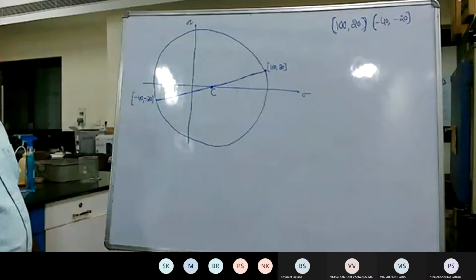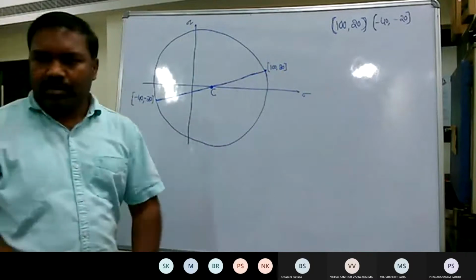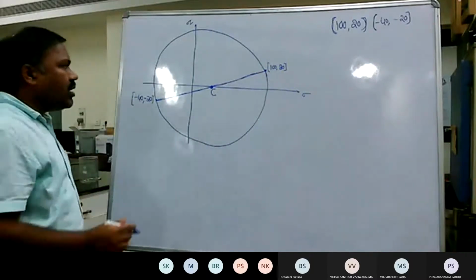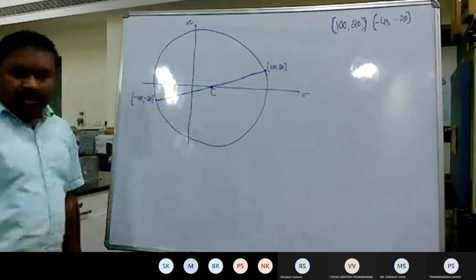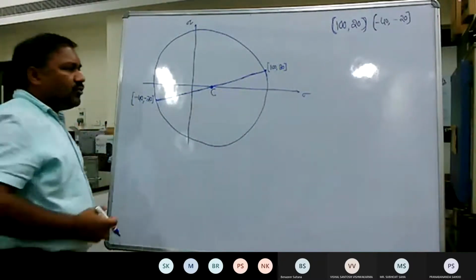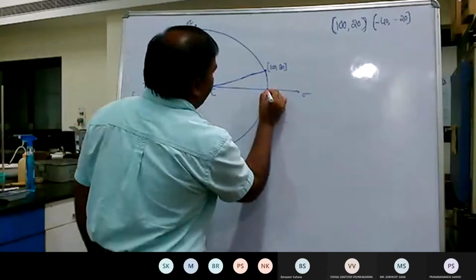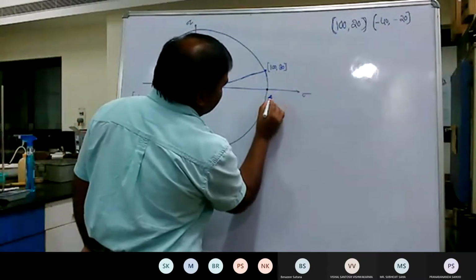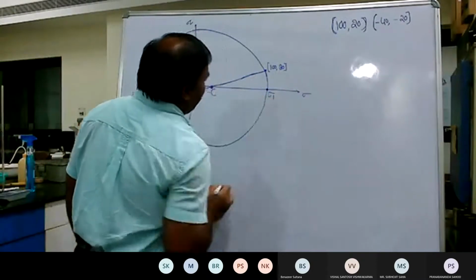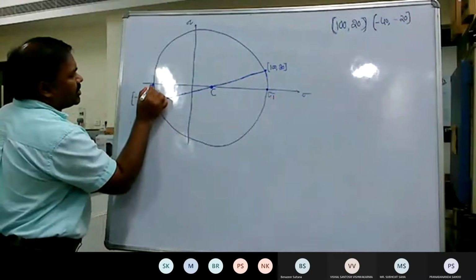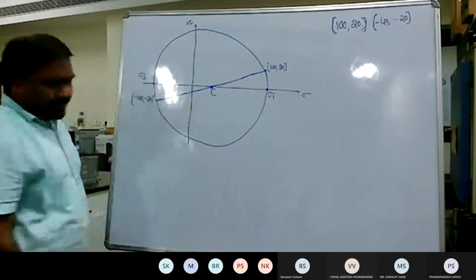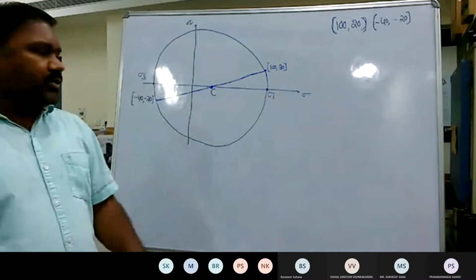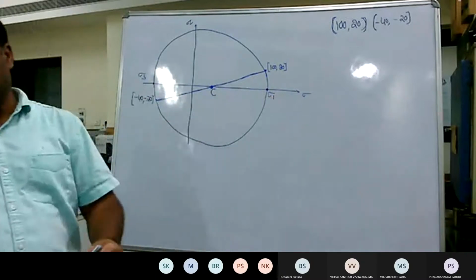So this is how you can construct the Mohr circle. Now wherever this circle is touching the normal axis, that would yield the maximum and minimum principal stress, that is sigma 1 and sigma 3. So this you need to do in a graphical way.